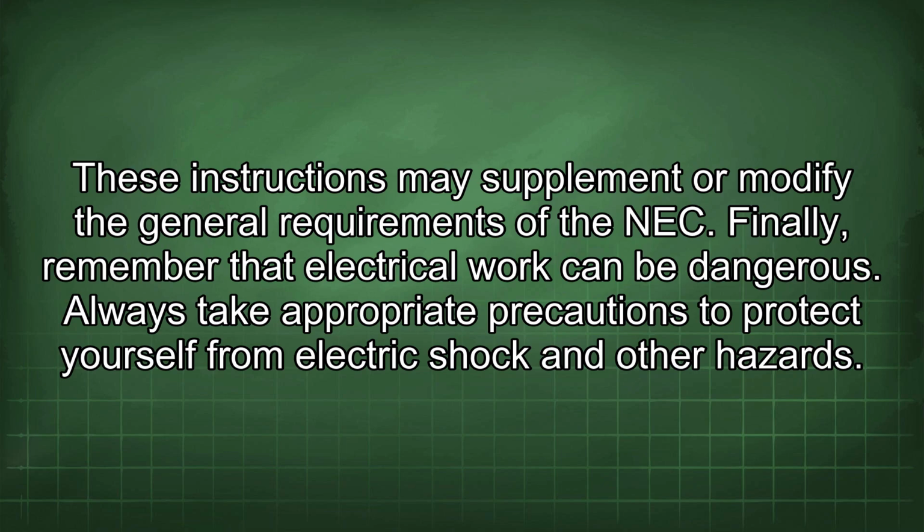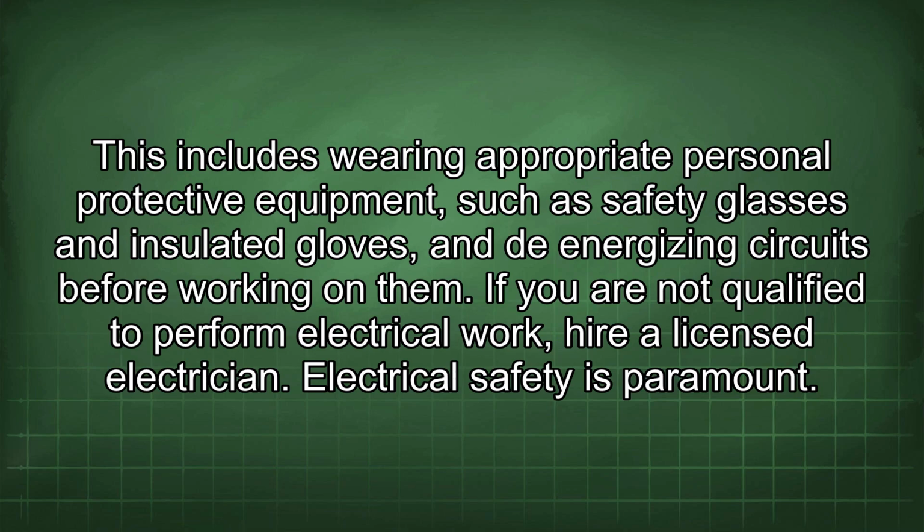Finally, remember that electrical work can be dangerous. Always take appropriate precautions to protect yourself from electric shock and other hazards. This includes wearing appropriate personal protective equipment such as safety glasses and insulated gloves, and de-energizing circuits before working on them. If you are not qualified to perform electrical work, hire a licensed electrician. Electrical safety is paramount.